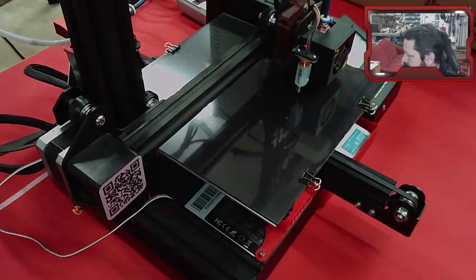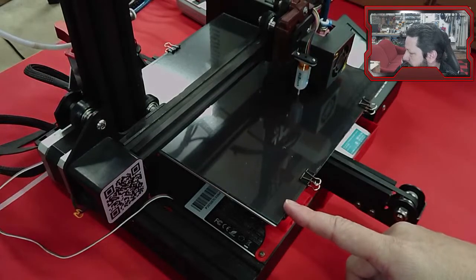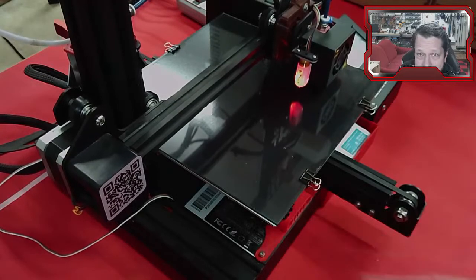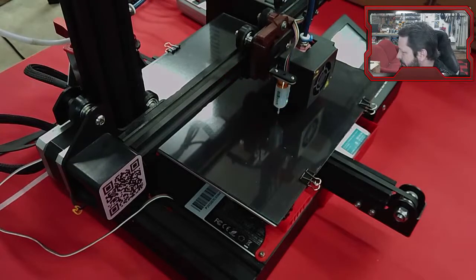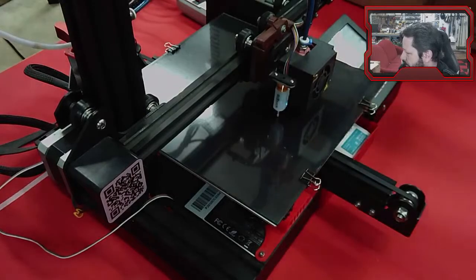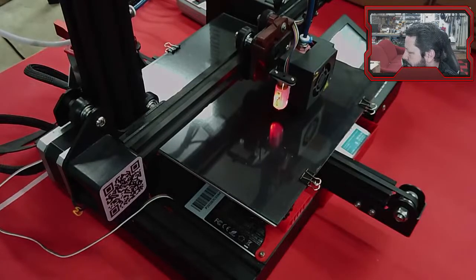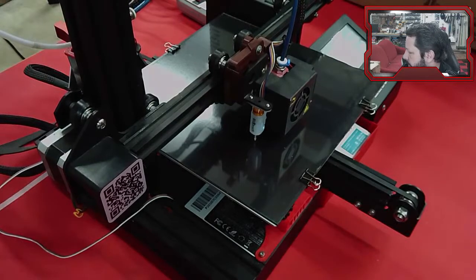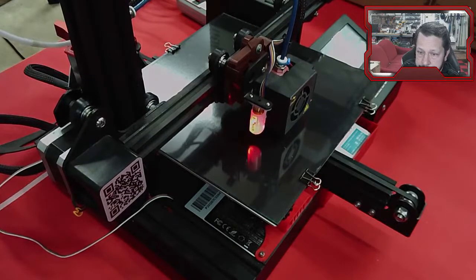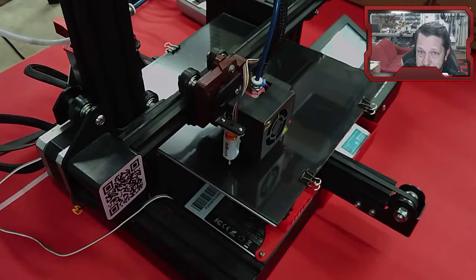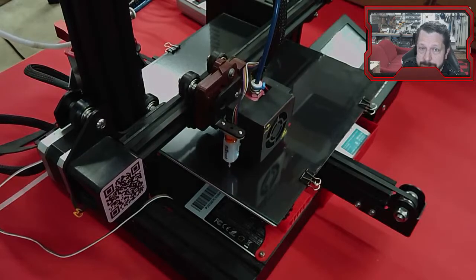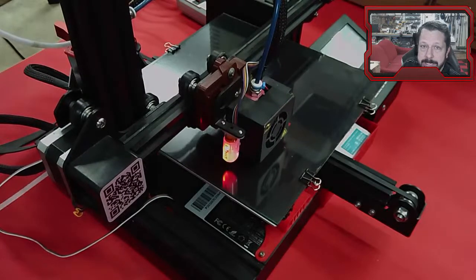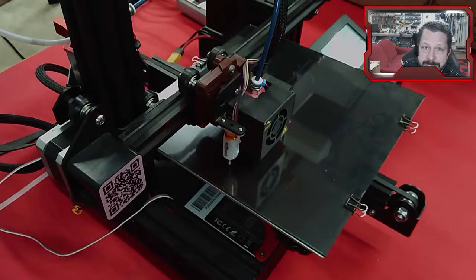to trace the contour of the bed so that the part is more likely to stick the first time. Now, I've got a sheet of glass on here, so generally glass is pretty flat, and you don't have to worry so much about the ups and downs of the metal. The thing with the metal bed is they're usually aluminum, and as they heat up, if you're doing a heated bed print, that aluminum bed is going to absorb a bunch of that heat and deform.